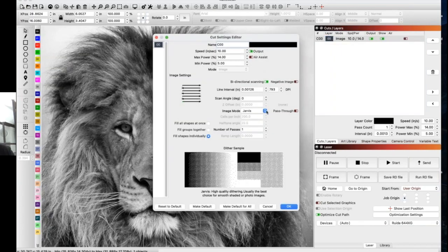I think we've gone through just about everything. Knowing which item to use, a negative image or a standard image. If you're doing it on acrylic or glass, remember that we're making the material lighter, so we want to bring out the light side, but typically the laser is engraving all of the dark stuff. So try to keep that in mind when you're trying to do an image. A lot of people ask which one do I use? Well, think about what it's engraving. Is it engraving the lighter highlights? What's going to show up on that material?